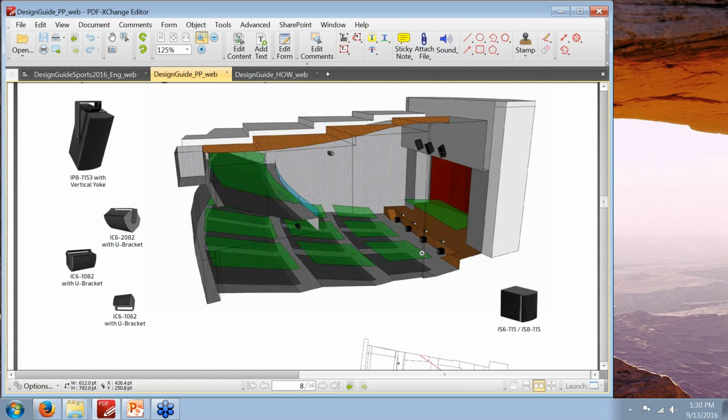If, quite frankly, you're in a scenario where you're not sure if you can include the stage rail coverage, maybe for some reason a compact I-series is a little higher on cost than they need, it's okay to step down to a lower cost compact cabinet out of the Veris line. It's really more important to get it working so the sound source is in the right place than to agonize over whether or not we're in the right product line. Yes. The main PA could be the larger high output cabinets. That's fine. There's plenty of coverage from that, but you're really just trying to psychologically, or with a trick of the mind, to get people to pay attention better with that stage rail system.